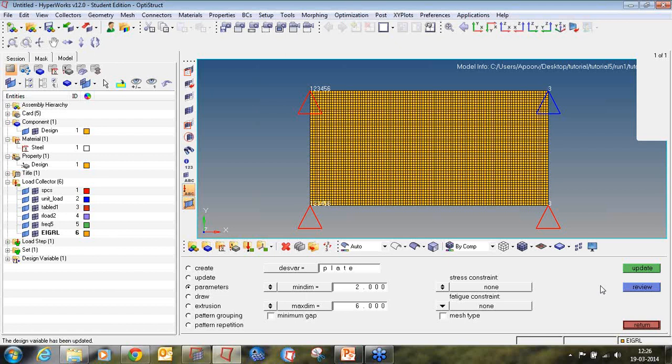The objective of this exercise is to determine where to locate ribs in the designable region. Therefore, a non-zero base thickness is defined, which is the original thickness of the shell. The maximum thickness defined by the T field on the PSHELL card should be the allowable depth of the ribs. Currently, the T field of the PSHELL is still 0.15, as you can see.